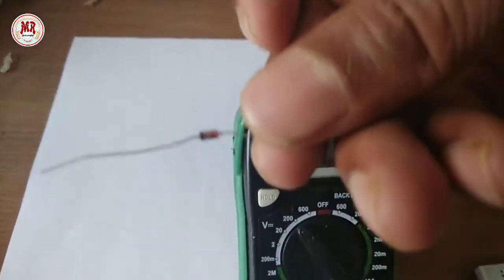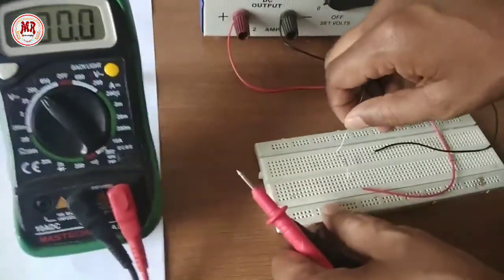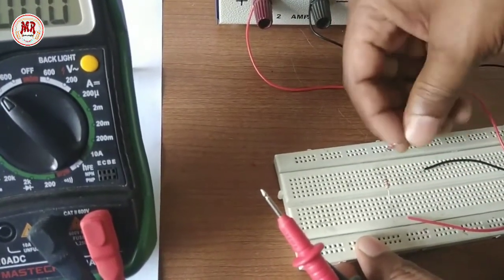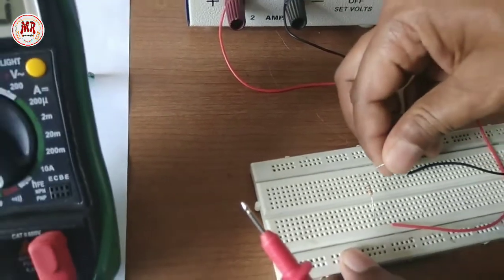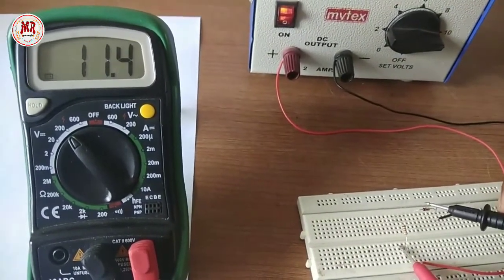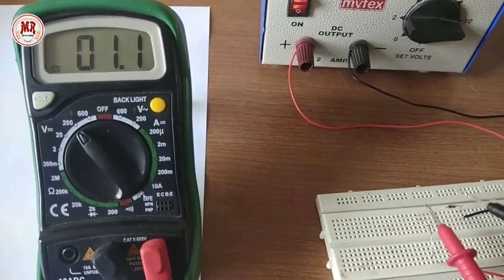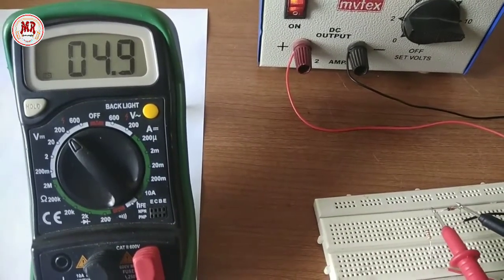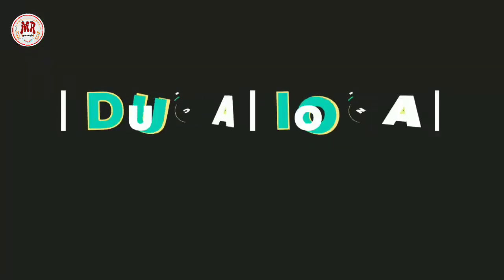Now again Zener diode of 5 volt, cathode, anode. It's supposed to give output of 5 volt across the Zener diode. For 12 volt input, the output across Zener diode is 5 volt. Now it is concluded that the Zener diode can be used as voltage regulator in reverse bias.